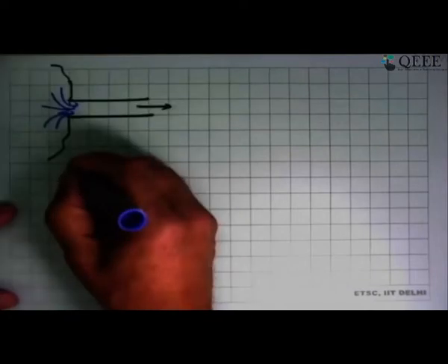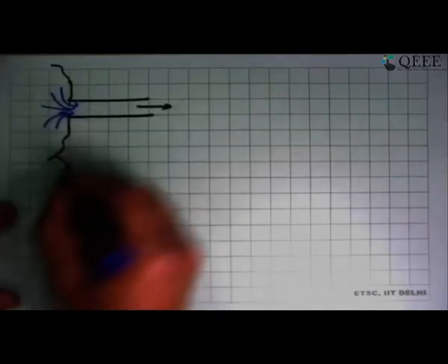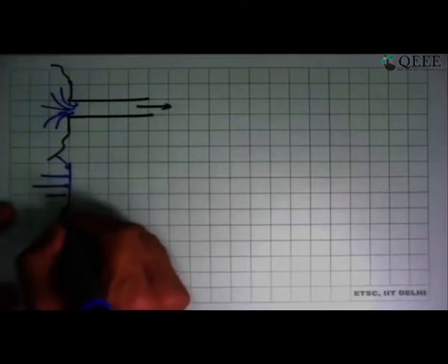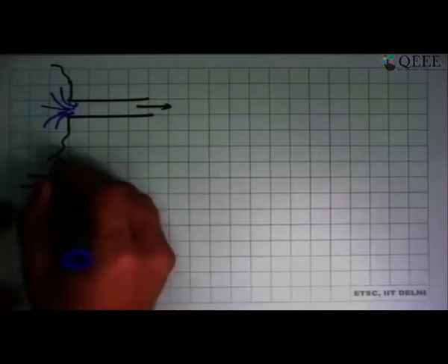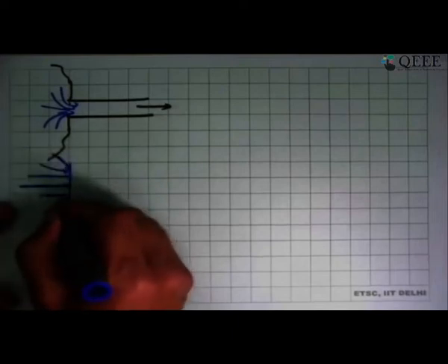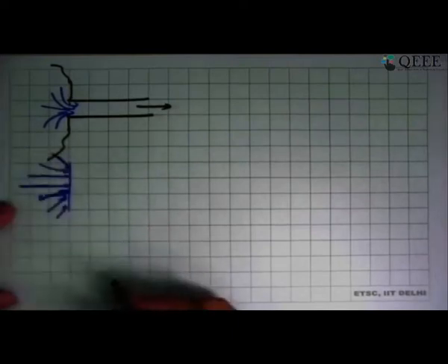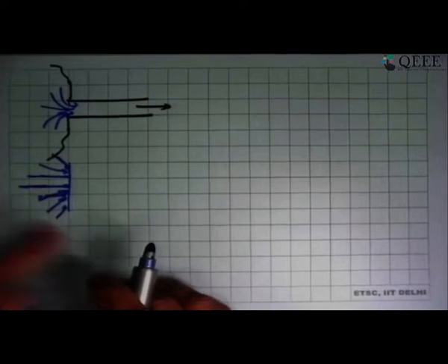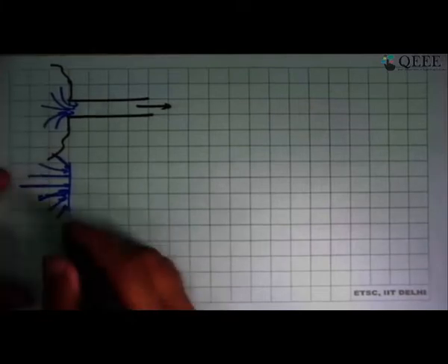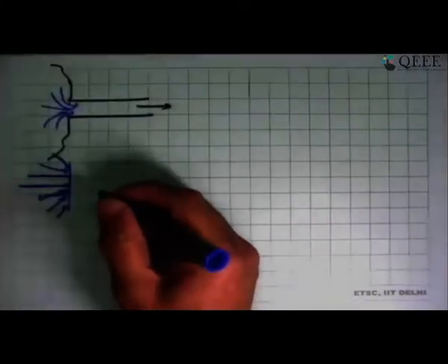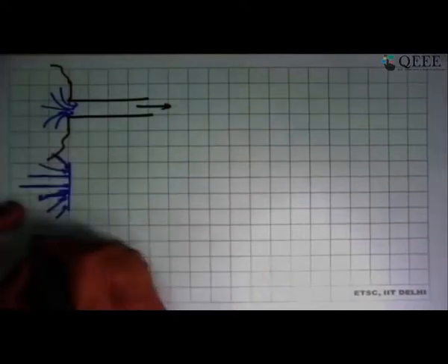At this plane, the velocity vectors will not be uniform. So here you will have this velocity vector, including if I am showing the magnitude also. The flow is neither uniform nor is the magnitude the same all over the place. This is what happens in this, which would be called a sudden entry or an abrupt entry.